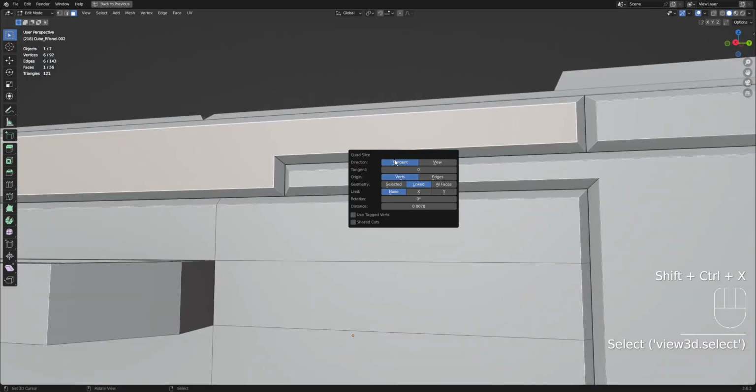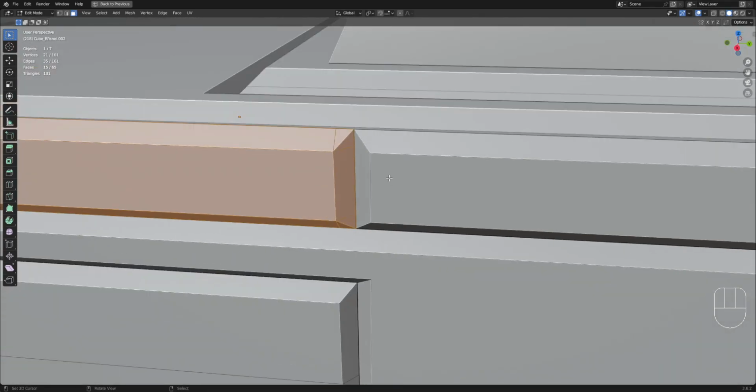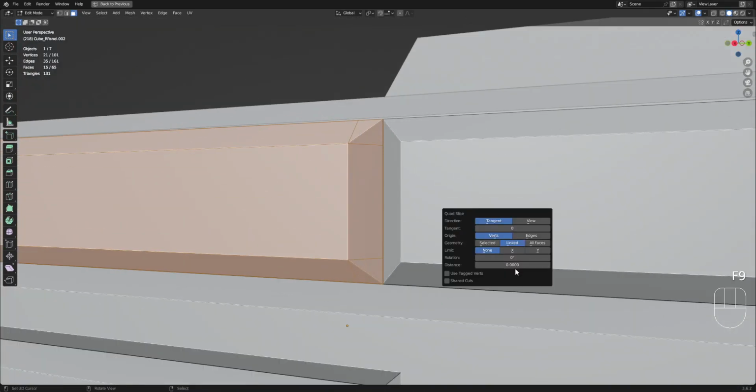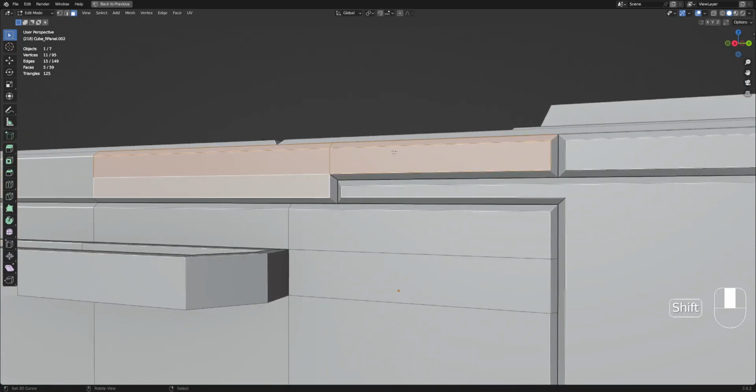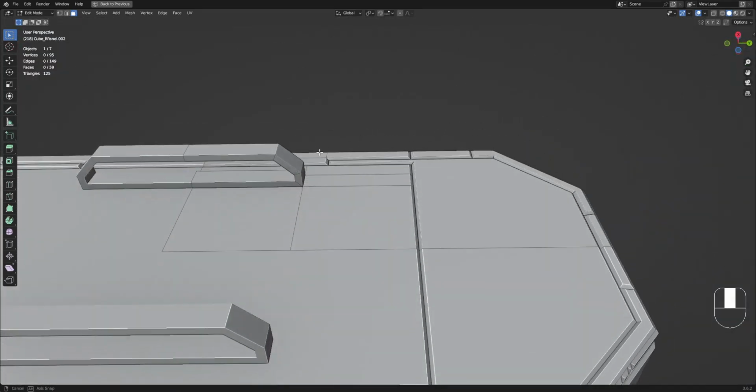So again, if you use quad slice and set this to the default value, you can see these edges here. And we can just increase this. So I often use 0.01. Okay, that's the quad structure.